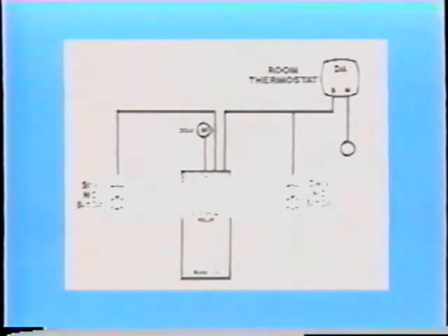The heating medium is steam, which requires a normally closed valve. On a rise in room temperature above set point, the room thermostat branch pressure will increase and open the normally closed chilled water valve. As the branch pressure rises, the output pressure from the reversing relay will decrease, allowing the steam valve to close. To effectively sequence these 2 devices, it is necessary to utilize a -5 pound bias.